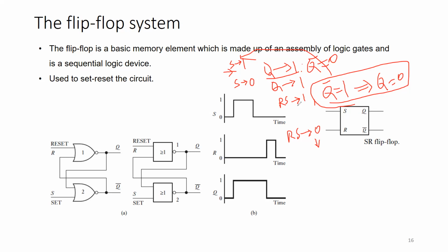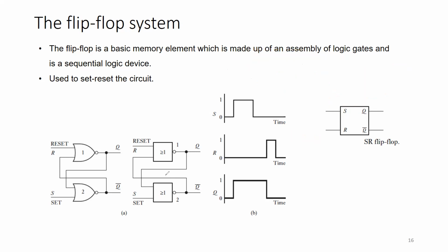Once you press the reset, only then this state will change. Now, once the state is changed, then again you have to press the set button. So this cycle keeps on going. Once reset works, set will work for only one time until reset is pressed, and reset will also work for one time until set is pressed. So this is a very important circuit which is used in mostly all the machine combinations.